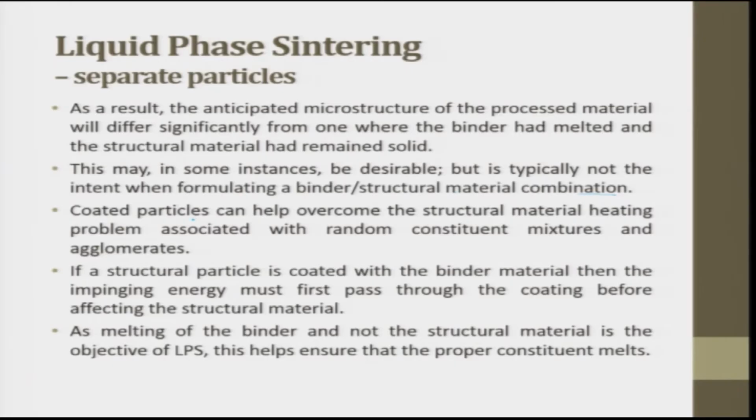The coated particles can help overcome the structural material heating problem associated with the random constituent mixing and agglomeration. If the structural particle is coated with a binder material, then the impinging energy must first pass through the coating before affecting the structural material. As melting of the binder and not the structural material is the objective of LPS, this helps to ensure that the proper constituent melting happens.